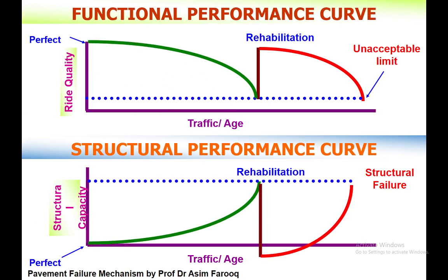This is very important. This specific word refers to so many things. On the basis of all those steps, we select the functional and structural performance. So the life after which rehabilitation or maintenance is needed, or below which the desirable standard needs to be improved, is very important, which we derive from the IRI, International Roughness Index, or the Pavement Condition Index.